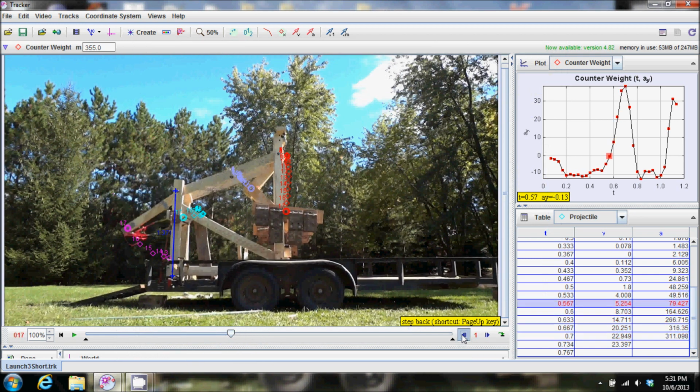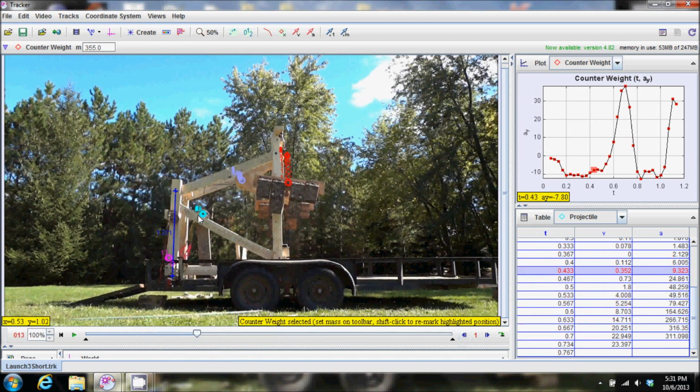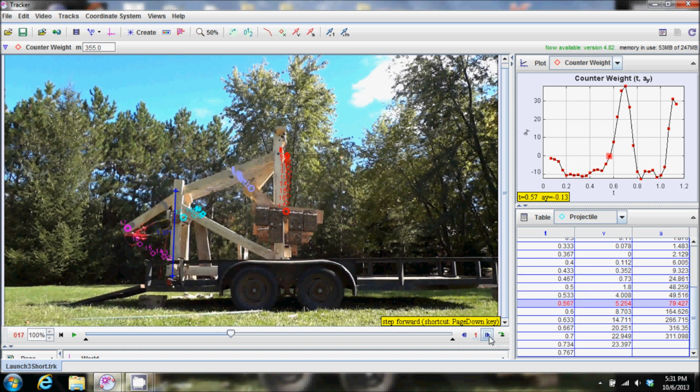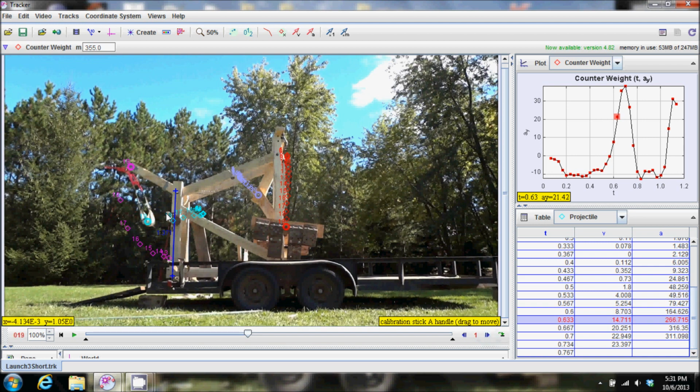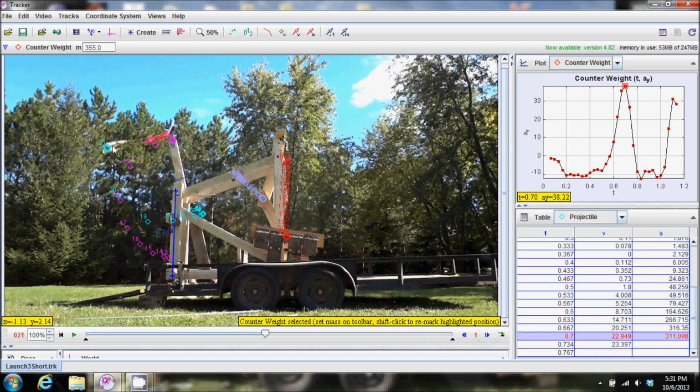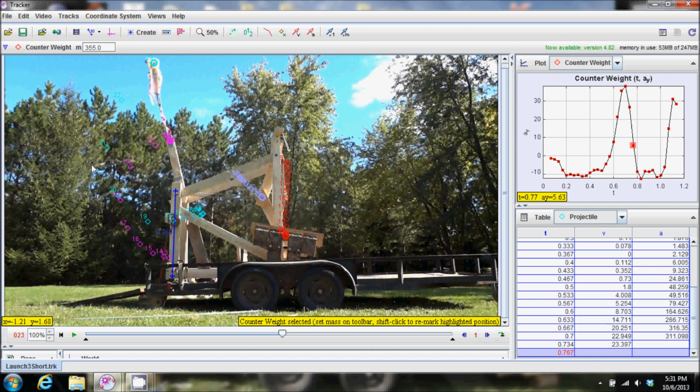We've started with the projectile right in close to the arm, and so it's not accelerating much, but when it starts coming out away from the arm, it's accelerating the most, pulling the hardest. You can see here where it's 90 degrees from the arm, where it's got the most leverage against the arm. That's also where we're getting the most upward acceleration on our counterweight, and then we swing the rest of the way around and release it.